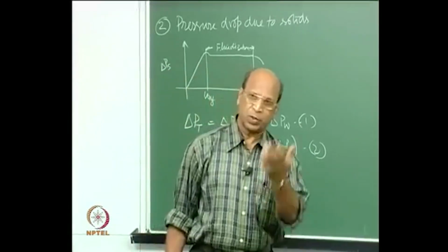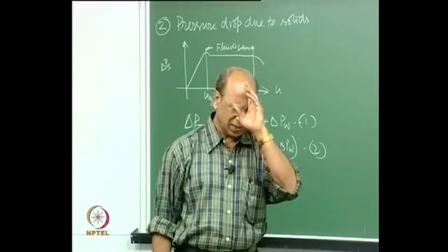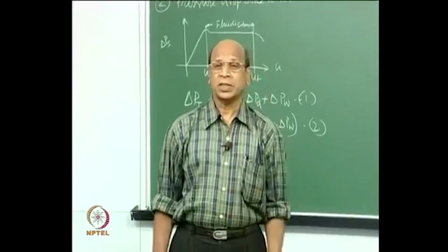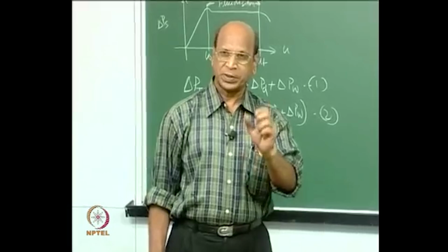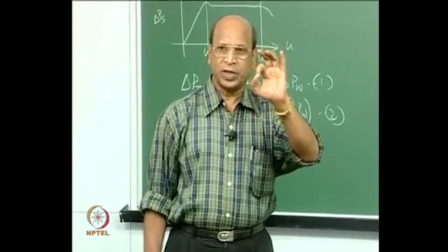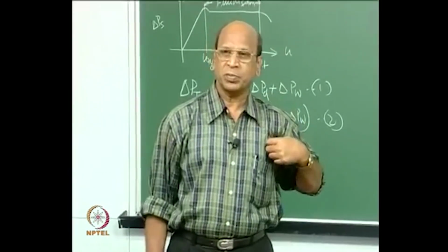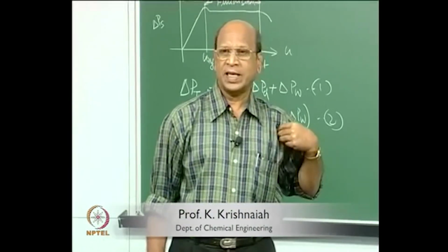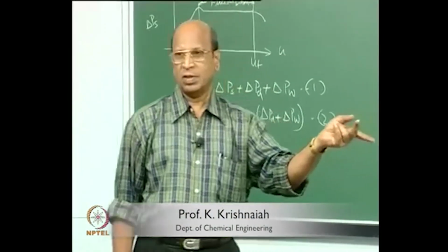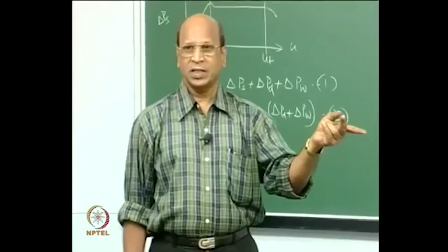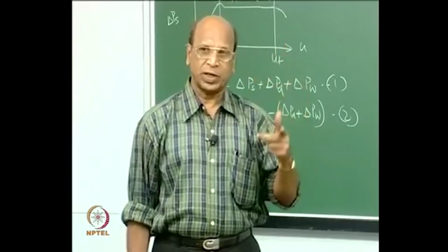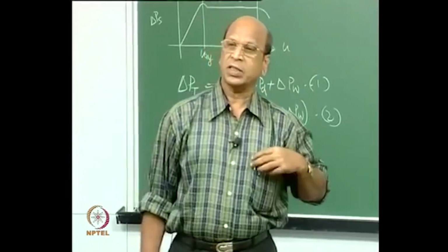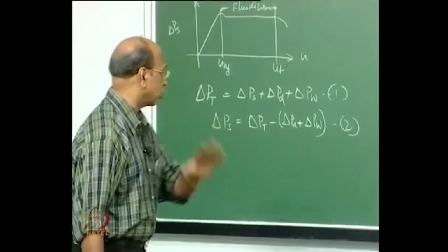I hope you remember your orifice equation, to measure pressure drop. We have a single orifice where you measure the pressure drops and convert that into flow rates. So, the same u square also comes here. That is why pressure drop will tremendously increase as the velocity increases, that we have to subtract. One has to be very clear.